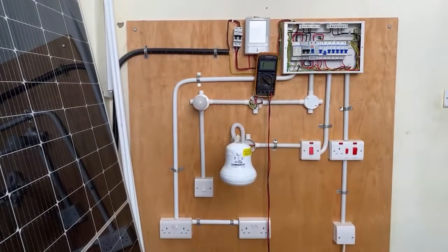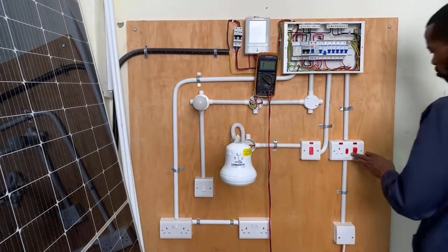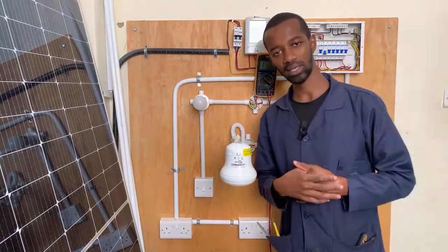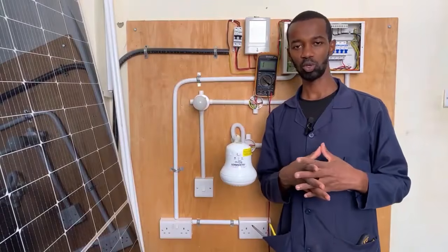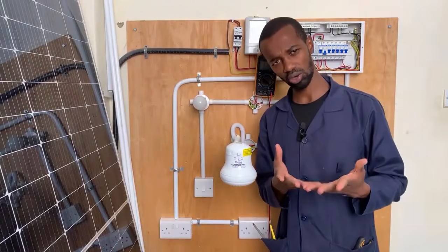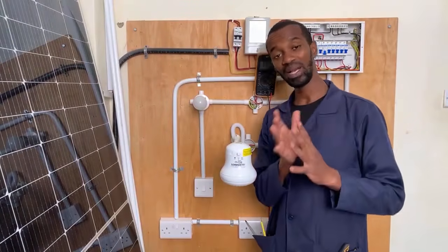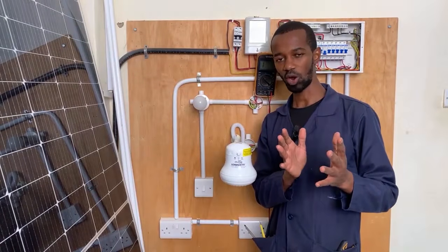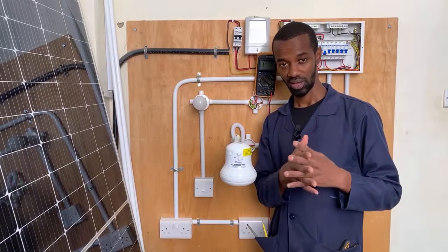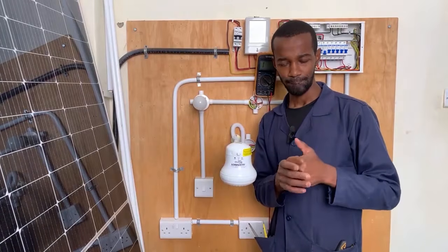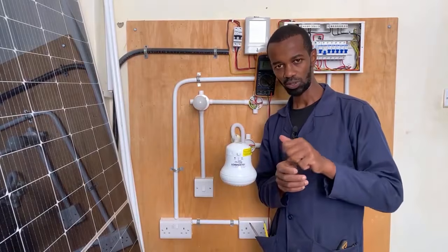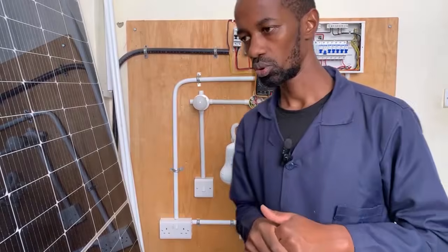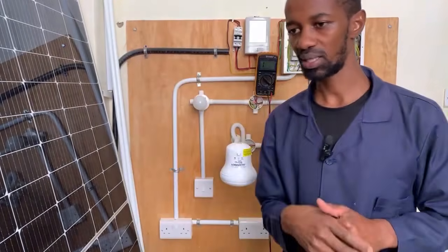So for instance, here you have a scenario whereby the cooker unit is on and the customer has said that my cooker is not working, it's not powering on. Those are some of the questions that you ask. Is it powering on? Is it only the hot plate, or even the baking section that is not working, or the oven, or both? What about the lighter, the one that normally sparks to allow power to the gas to light up?